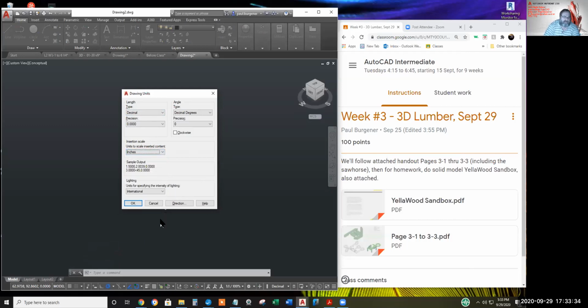And that way, if you mail order a sofa from Japan, and the dimensions are, I don't know, 85 millimeters. Is that realistic? No. 85 centimeters, 2 meters. Anyway, it's drawn in metric units. And your floor plan or your 3D house model is drawn with the assumption an AutoCAD unit is an inch or an AutoCAD unit is a foot.